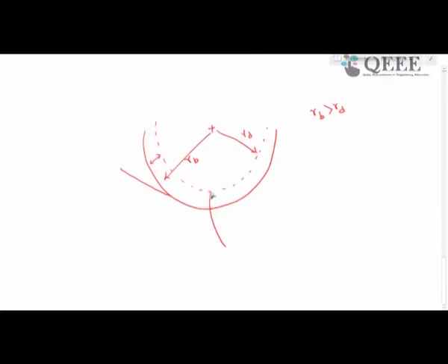So if at all there is a tooth profile, that tooth profile is not involute, right. So we take this to be just a radially extended version of whatever happens here, right. So that radial extension causes a lot of problems, because now if there is engagement happening in this portion, it is not involute. So as a result you will have lots of problems, and this is what eventually will lead to interference. So let us look at that aspect.